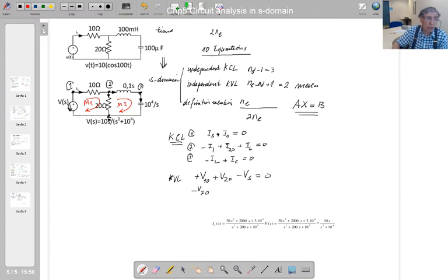We are writing now the Kirchhoff voltage law equation for mesh 2 direction, and the 20 ohm resistor current is opposite direction, so it is minus. And mesh 2 direction and the inductor current direction is the same, so it is plus VL, and similarly plus VC is equal to 0. So we wrote these two equations now.